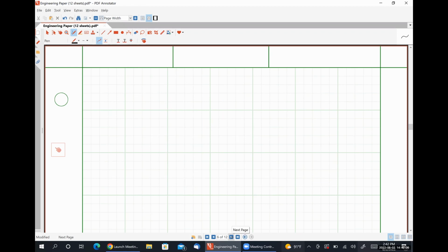So we know that the effective value of a sinusoidal function is just the magnitude of the sinusoid divided by the square root of 2. Early on in class yesterday, we learned that the average power absorbed by a generic network was given by 1/2 Vm Im cosine(theta v minus theta I).